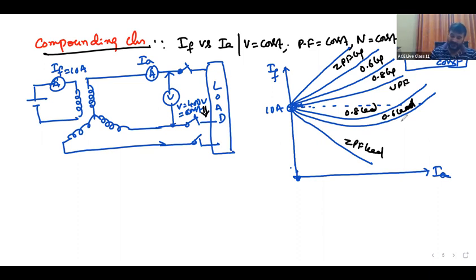They are increasing the field current. Increasing, keep on increasing. Okay. But what happened to the voltage, sir? Voltage decreases, drops. No, sorry, you need to maintain the voltage constant. Voltage constant means the drop can be compensated. How can you bring it again to 400 volts? Field current has to be increased. That is what we are doing.